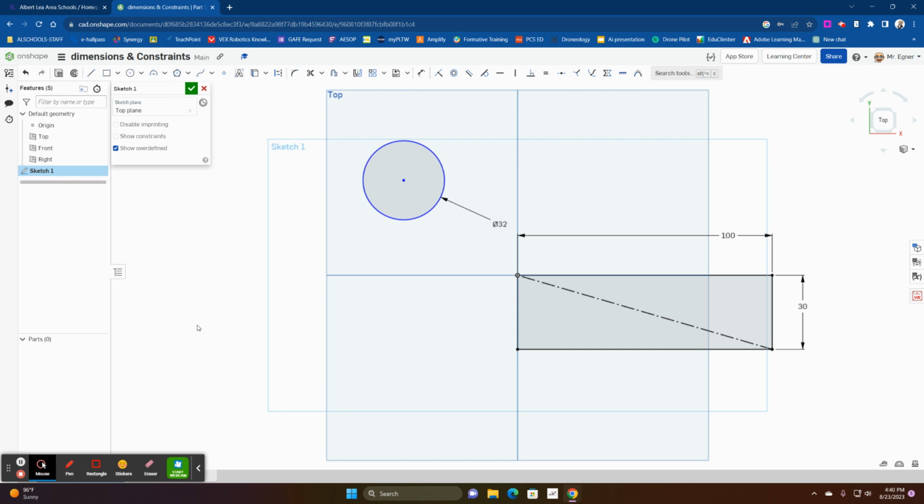So now I've got my construction line through there. Now with that construction line, we're going to use that as our midpoint. Remember, the construction line does not show up in our model. It shows up as a point of reference for us. So now I can put my pieces way away from each other. I'm going to have them separated way far apart, to show you how good this is at joining them. So I use this midpoint.